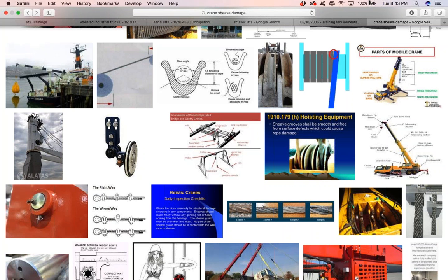We also have to know and obey all state, federal, and local laws. Also, we want to follow the guidelines for driving equipment on a site. We never drive a machine in a congested area around people without a spotter or a flagger. We talked about that a little earlier. Now we're talking specifically about a crane. The spotter or flagger is responsible for determining the direction and the driver speed, but usually we'll have a work order or a work plan that's going to advise us on the route that we're going to take, barring any significant change.